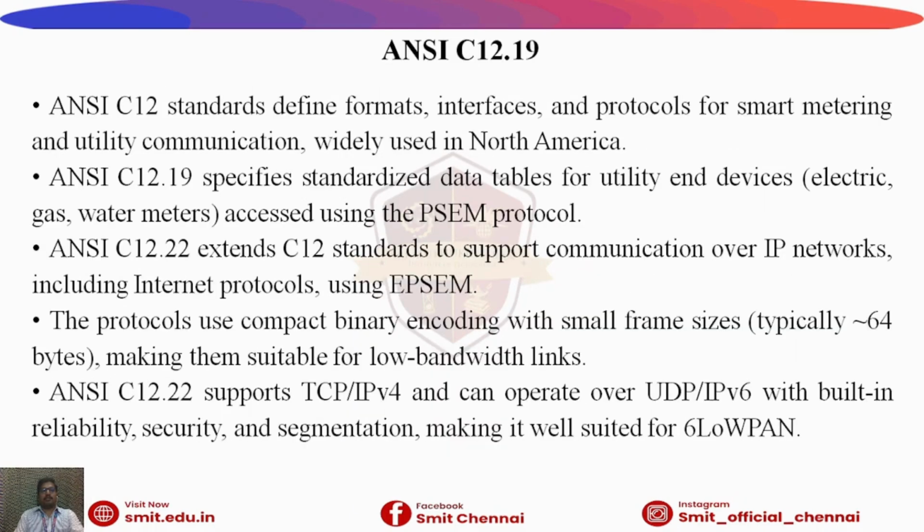The next protocol is ANSI C12.19. ANSI C12 standards are used for smart metering in North America. C12.19 defines standardized data tables for utility meters. C12.22 supports IP-based communication using compact binary encoding. Small frame sizes make it suitable for low bandwidth networks. It supports reliability and security features.